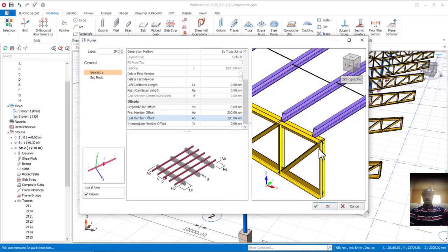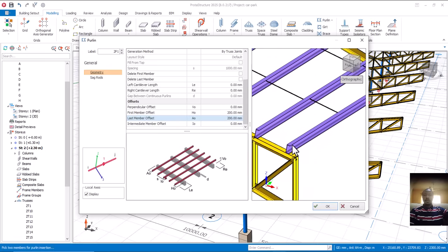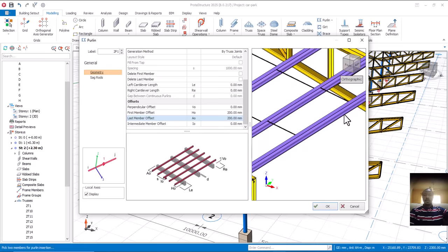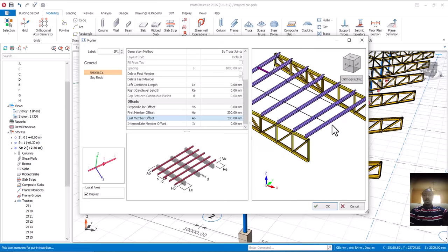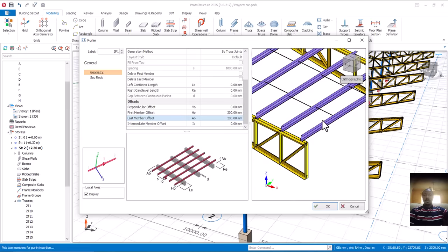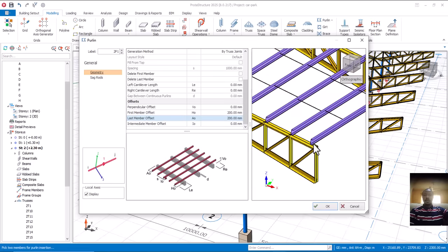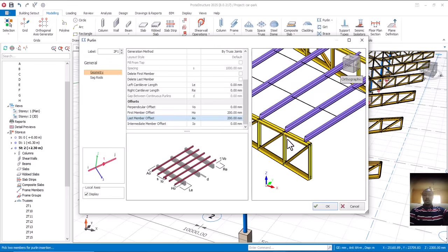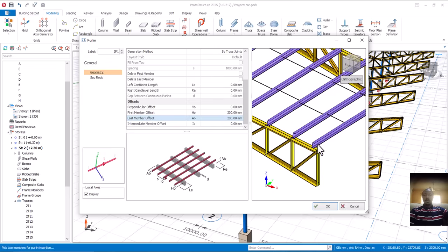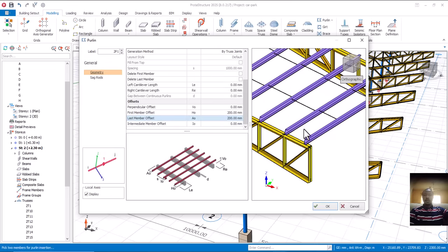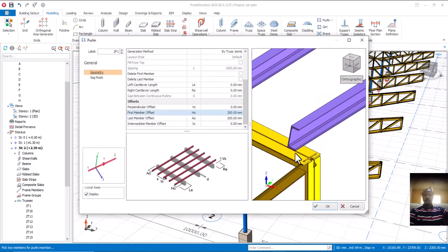Is that okay? So now if you imagine that extension of that zinc, these edges here are prone to what? To wind, and wind will start affecting your structure from this point here. So that is why, to have a good connection, to have a good resistance between the zinc and the wind, there's need for us to shift this particular first line to the edge of these trusses.